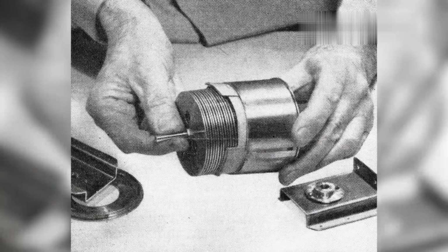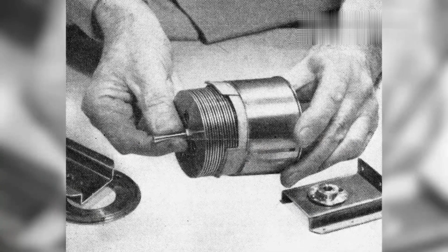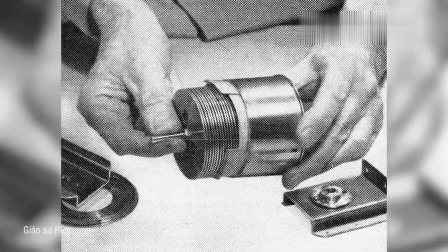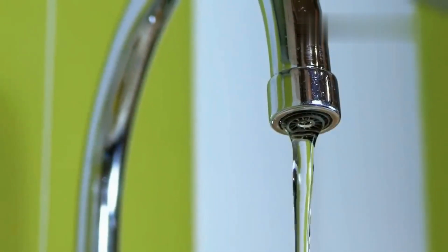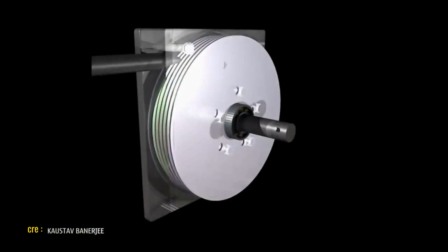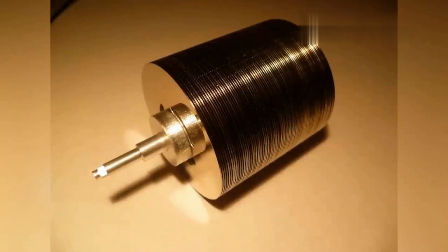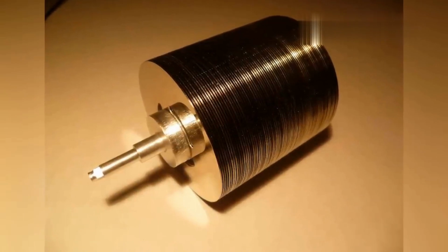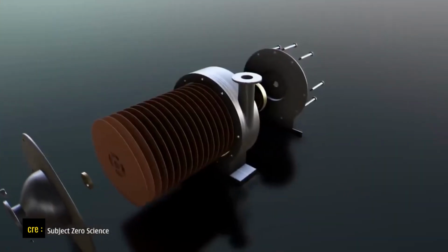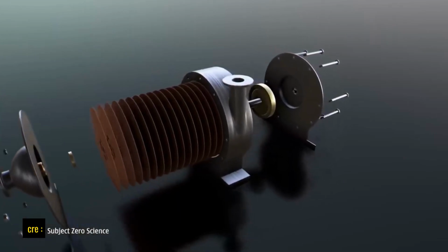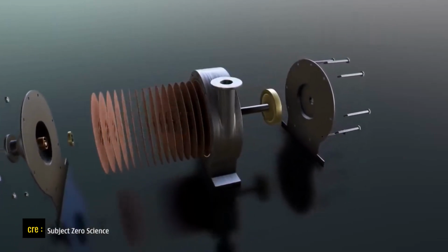In a research work published in 1991, just before retirement, Professor Rice conducted an analysis of Tesla fans and a cascade flow model. He suggested that the rotor efficiency of Tesla fans using cascade flow could be very high, even exceeding 95%. However, to achieve this efficiency, the design of the fan would need to include numerous disks, and that's when problems arise. A greater number of disks implies a higher likelihood of imperfections on the surface or edges of the disks.